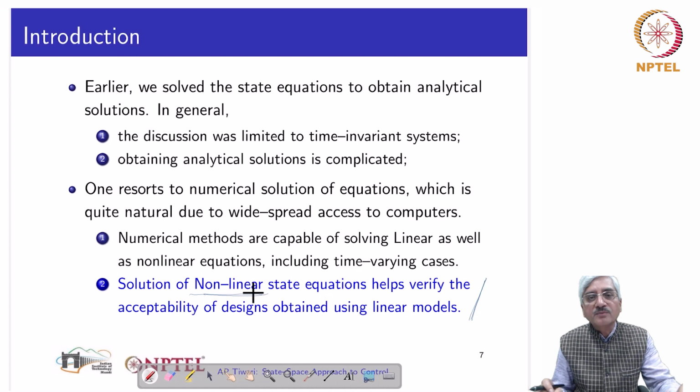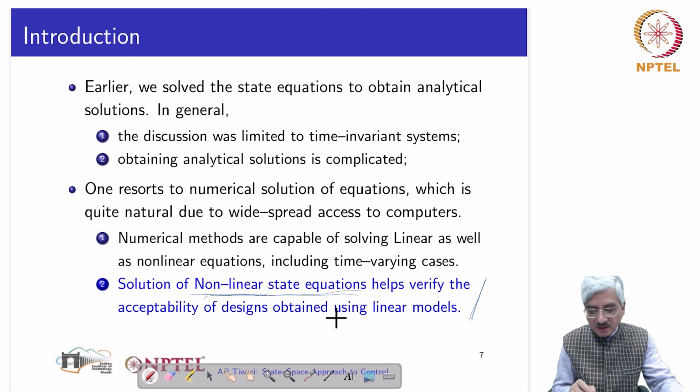Now there has to be a confidence that a linear design will work for the nonlinear system. So what we do, we simulate the nonlinear state equations, and on that we verify the designs obtained using the linear models. It builds our confidence.